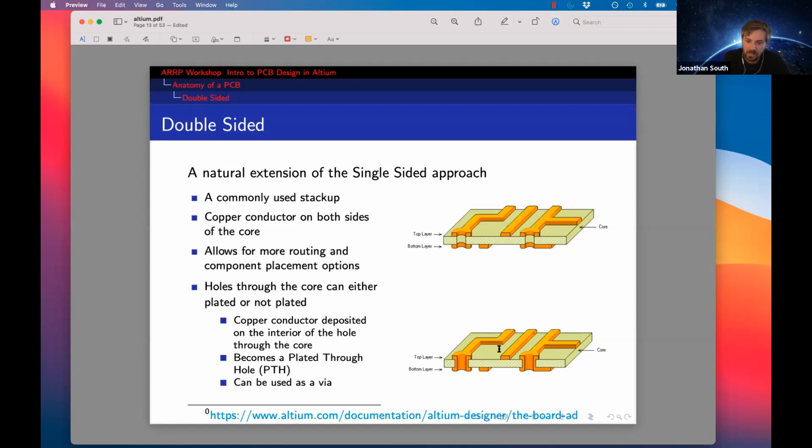So remember, these aren't like wires where you can physically take one wire over the top of another. You can't cross traces unless they're electrically meant to connect. So if you're trying to get traces everywhere, you need a bit of flexibility in the routing. So having two sides of the board to deal with can be quite handy and often necessary for more complicated circuits.